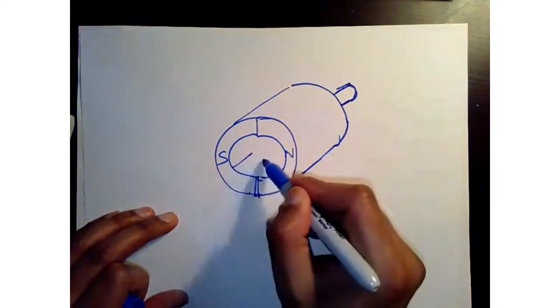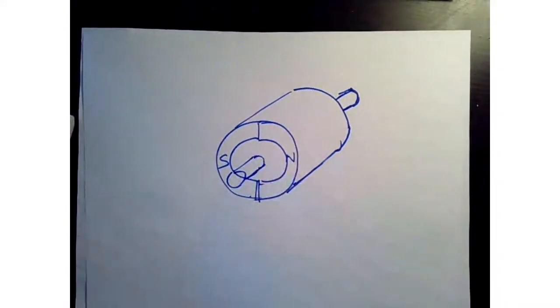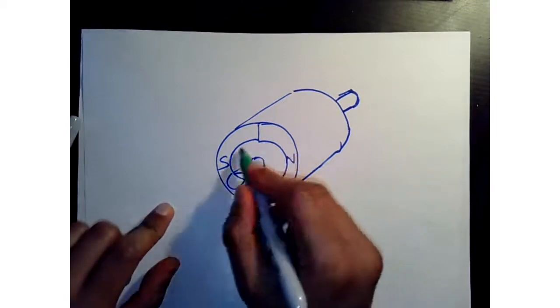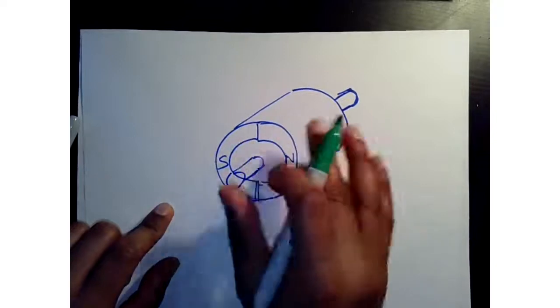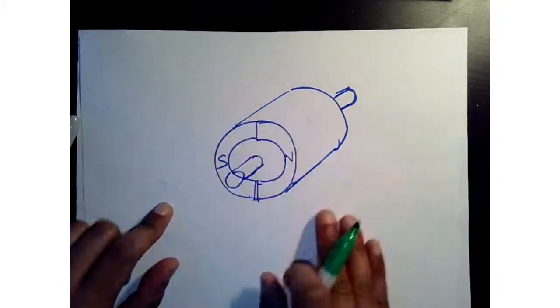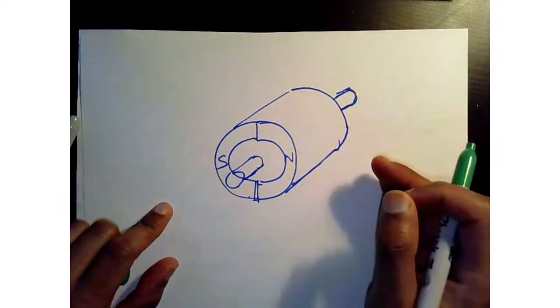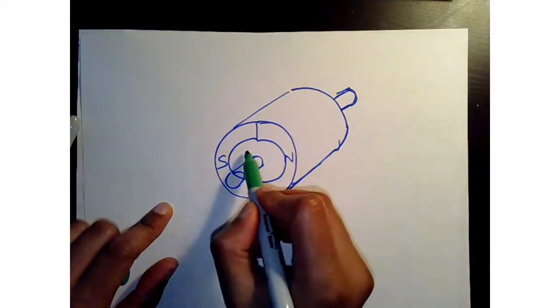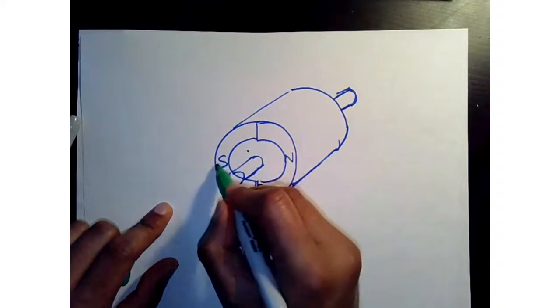Now, here we have our rotor like that, and we have the shaft attached. You need some kind of a sensing mechanism on this to see where or how the rotor is rotating. This is the rotor only. I didn't draw the stator, because the stator is what generates the stator flux, where the windings are. So we need some kind of a position sensor that mounts on it.